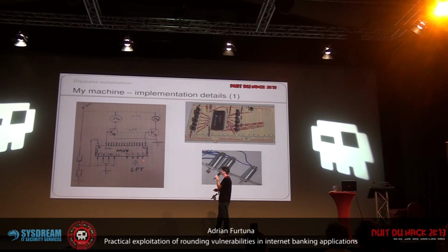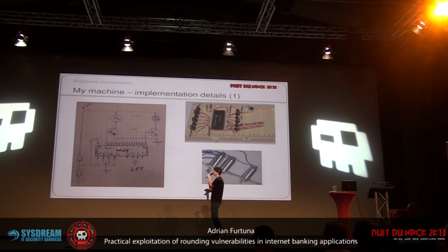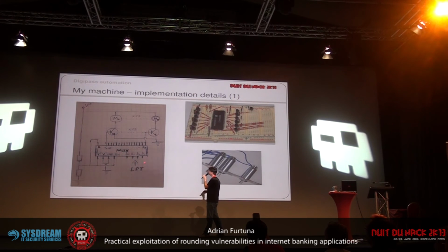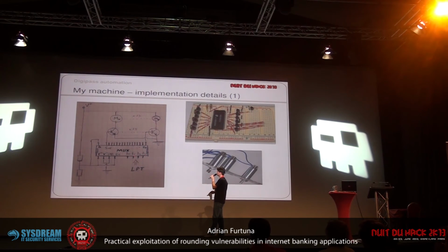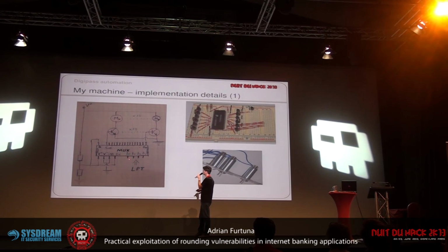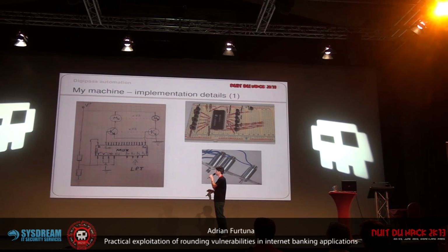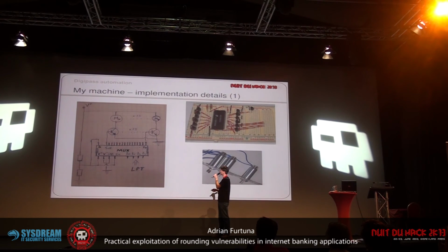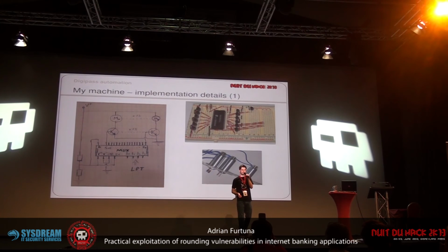So according to the code that comes here, for instance, if I receive 1001, this is a multiplexer which connects the input with one of the outputs depending on the selection pins. So using the 4 pins, I can select a maximum of 16 outputs, but I do not really need all of them.